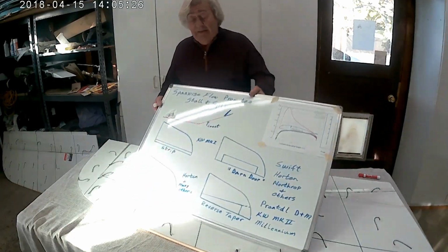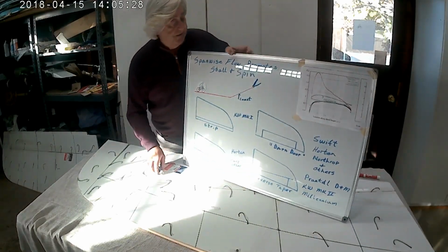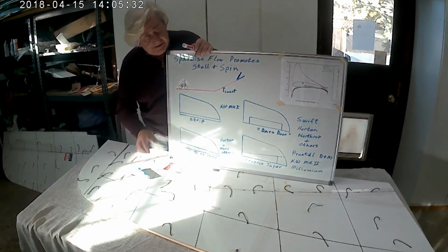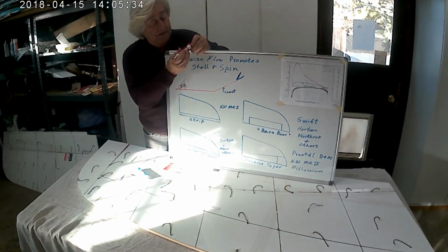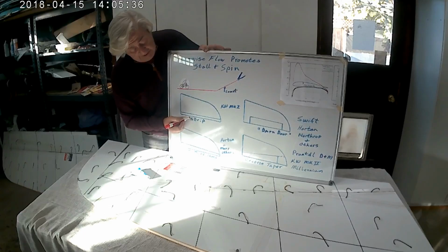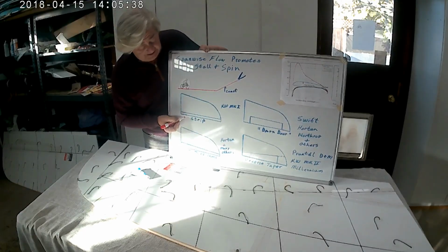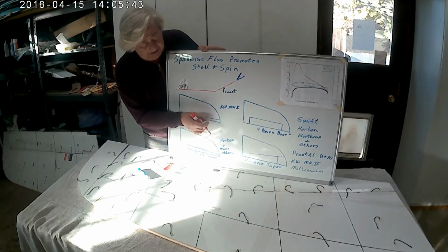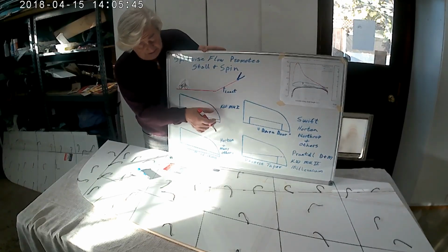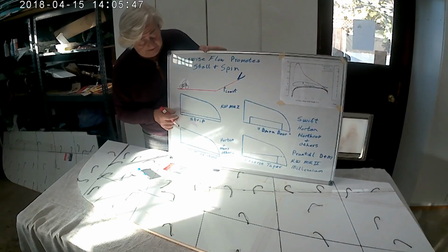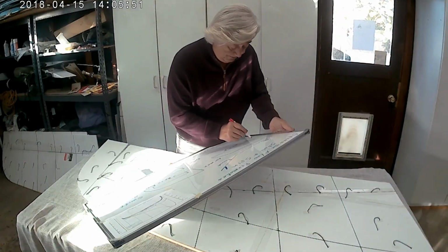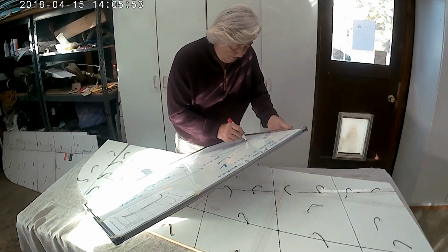Now, here's the types of elevons that you can see on flying wings sometimes. This is what I had on my original flying wing. I had essentially a strip elevon, 6 inches wide, entire span. This is what I like to call, here, I'll write it down here.